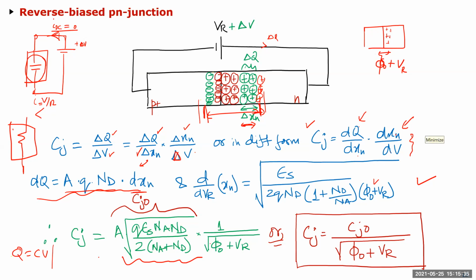So when we do circuit theory, we'll take these examples and show you how it applies or doesn't apply. Ohm's law is just finding out the current-voltage relationship in a resistive element, right? It doesn't tell you anything about whether a system is linear or not. The only way to find out if a system is linear or not is by applying the superposition principle.